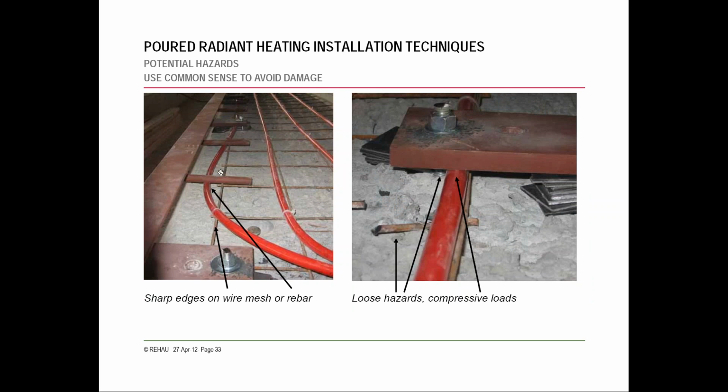Here is another suspended slab, and you just want to make sure if you're rubbing up against any surfaces like that, go ahead and either move it or put a PE sleeve on it, as I mentioned earlier, or even a piece of scrap PVC is fine as well, just to keep everything away from it until the slab goes in over it.